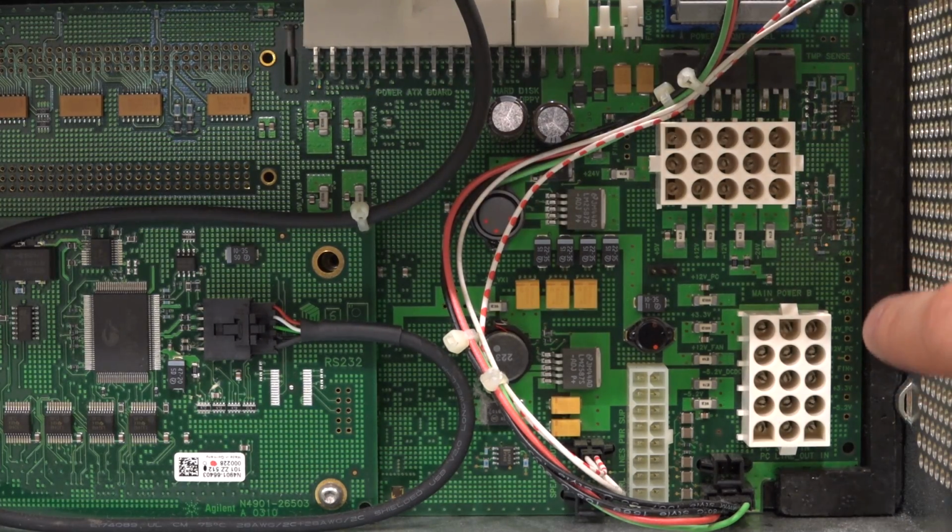Now all the power supply voltages are actually written on the motherboard, and you can read them, all different ones, and each of them is individually fused, which is of course what high performance good equipment will always do, to protect the power supply and protect the instrument from cascade failure. So we can go ahead and actually measure every one of those fuses just to make sure that something didn't go horribly wrong inside the chassis and cause the problem on the power supply.